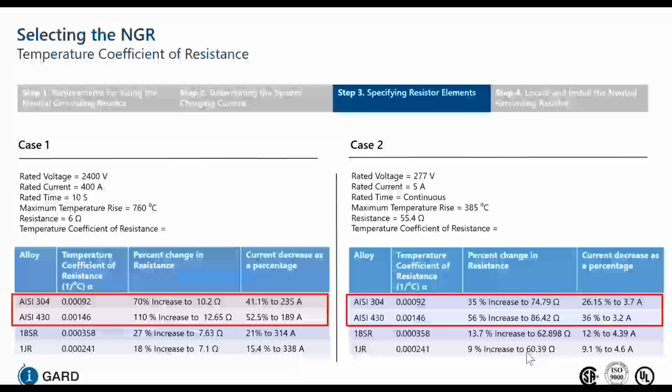throughout the fault. Why this is important is because, for example, you have a utility transformer and you have reclosures. After the first or second reclosure time, the third one, the temperature of the resistor is going to be warmer. And when it is hotter, it may not give you the right amount of current for the next fault. So you may ride through it not believing there's a fault, depending on what you set your protection for.